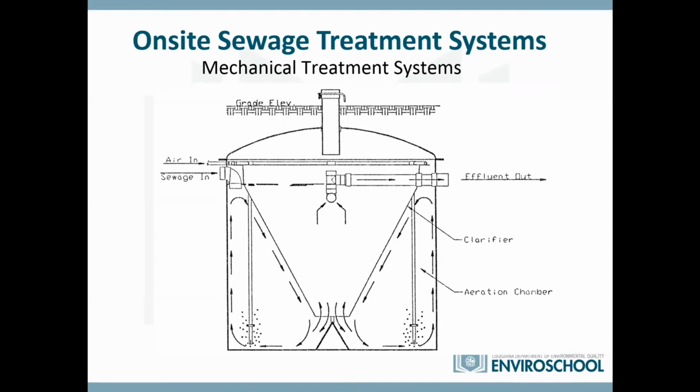And eventually some of that water starts filling into that cone in the center. And as it slows down, the solids, again, if there are any solids left over, return back into the outside so that it's recirculated again to be broken down further. Meanwhile, the more clear water goes up into the center and flows out by gravity to the effluent pipe.